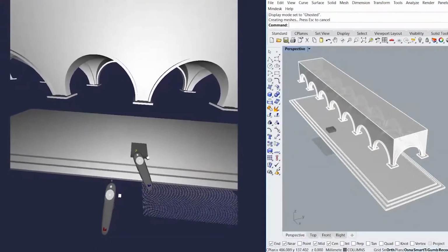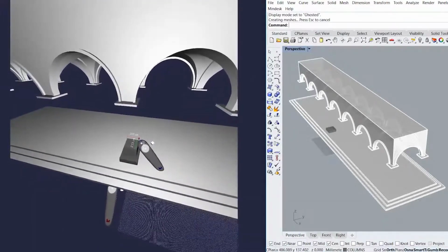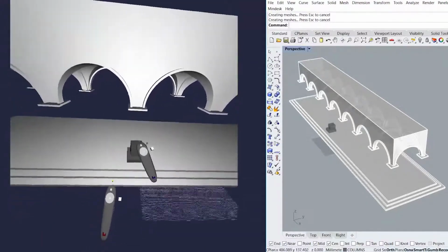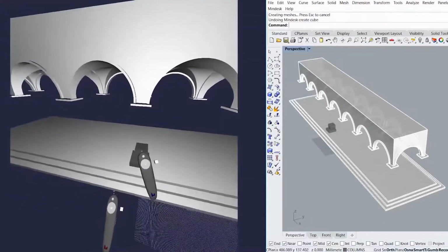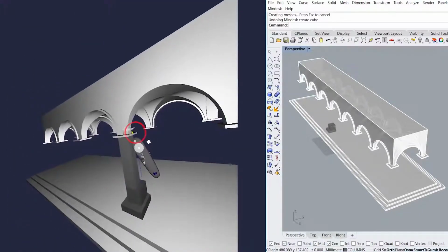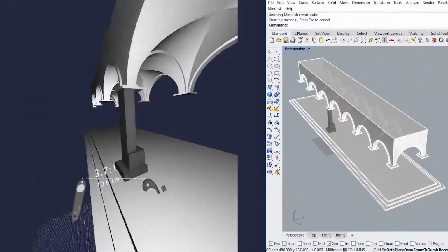And using my thumb pad to reactivate the same box, I'm going to click the bottom left box corner and then the top right box corner. Again, using my thumb pad to reactivate the box and using the snappy draggy feature, I'm going to align with the underside of the column top. After loosely modeling those 3 boxes, I need to still align them together.